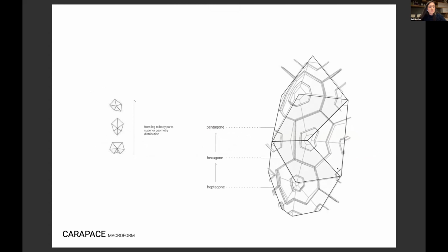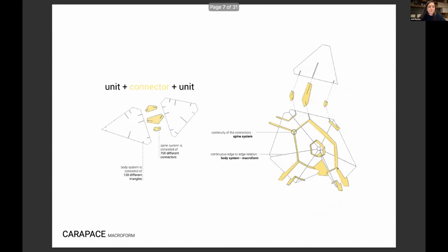Triangle body units and connector units were limited in their sizes because a plywood panel becomes bendable when its size gets bigger, even if they are locked with perpendicular surfaces. So the maximum edge dimension was not more than 60 centimeters, according to the material's behavior.